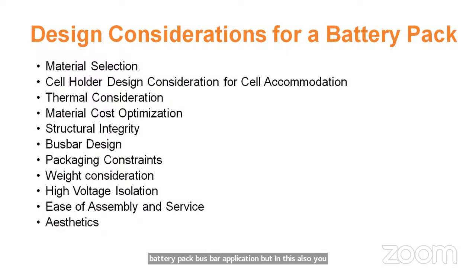You have to connect the bus bar with the cell, right? And to connect the bus bar with the cell, various technologies are there, like laser welding, wire bonding, and resistance spot welding. So what process you are going to use for this connection of the cell and the bus bar, that process also determines what material of the bus bar I have to use, correct? So those things you have to talk about.